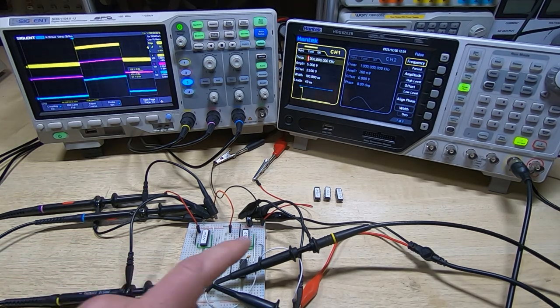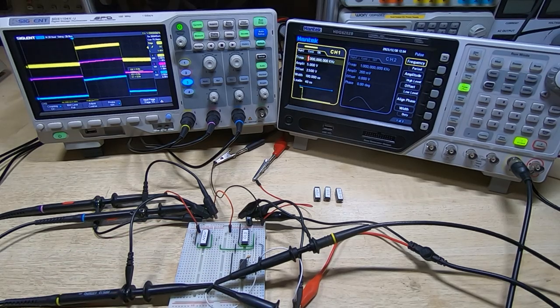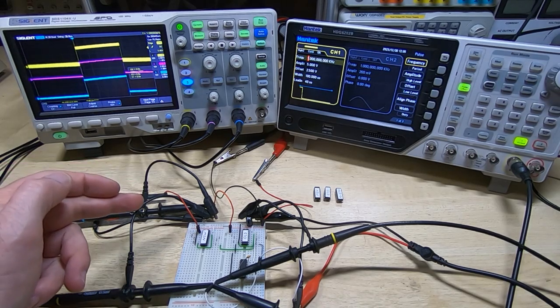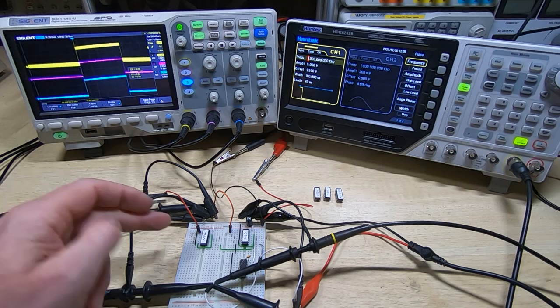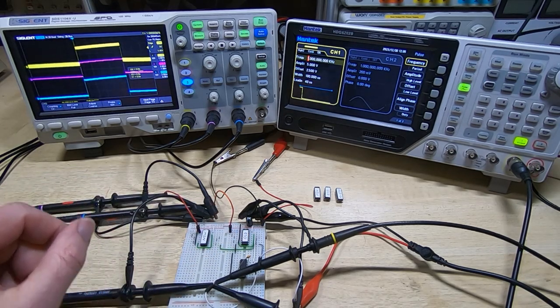Now, it's not the clock directly from the signal generator, it's going through a TTL 74LS04 just to clean it up and make the signals consistent throughout the circuit. And the purple and blue traces are the output of the 2 ICs, one new, one old.